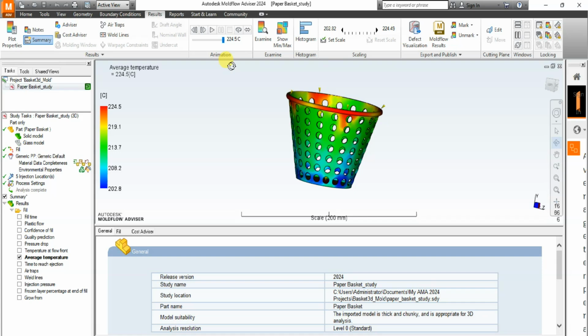Now the other thing is decreasing the injection time, and the effect might be that this might cause excess shear at gates if it is restrictive. Too much shear can cause degradation and surface defects. Now the other thing you should take note of is increasing the thickness in the area to permit flow. This might cause functional problems with design and increase the cost. So if you are increasing the thickness of the area to permit flow, this might also cause functional problems with design and increase the cost of production.